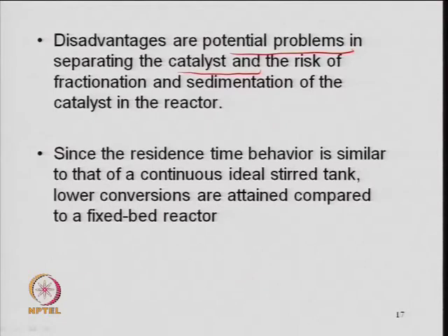But again there are some disadvantages, because you have fine powder, smaller particle size. So, there is the separation of the catalyst and the risk of fractionation and sedimentation of the catalyst in the reactor. If the stirrer is not well designed, or if the density of the catalyst is high, then there may be a chance that some of the catalyst will get sedimented, or if it is very fine, it may get out along with the liquid.